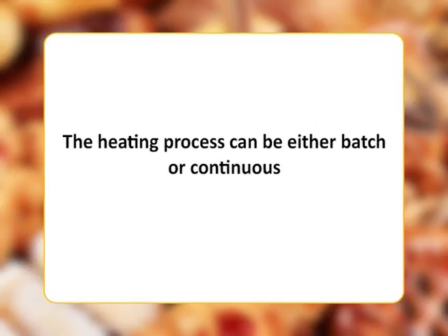In heat sterilization, it is important to ensure that the food is adequately heat treated and to reduce post-processing contamination. The food should then be cooled quickly and it may require refrigerated storage or should be stable at ambient temperature. The heating process can either be batch or continuous. In all thermal processes, the aim should be to heat and cool the product as quickly as possible.